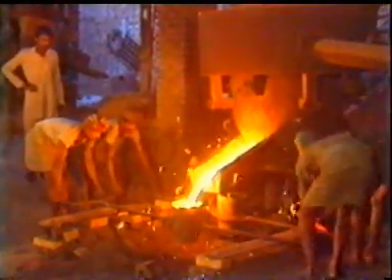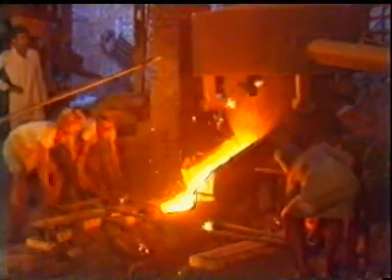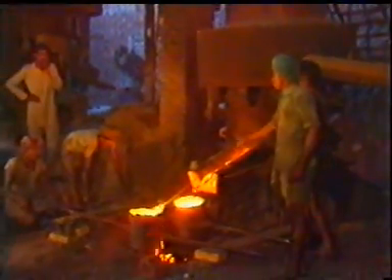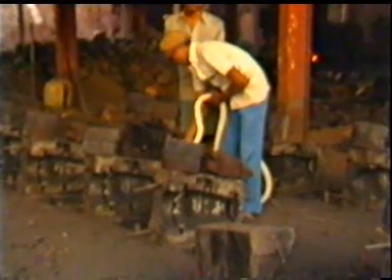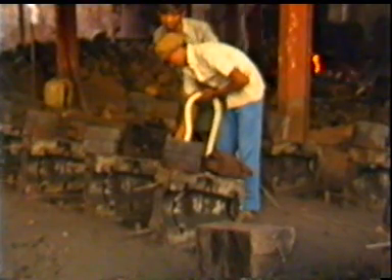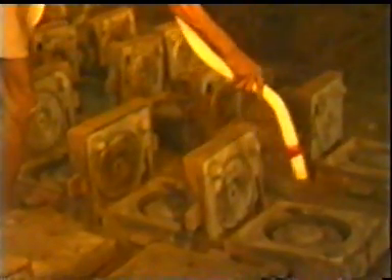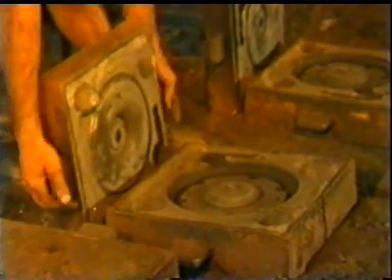The metal from which the component is to be made is melted in a furnace. The furnace may be coal-fired, oil-fired, or electric furnace. Here we have a coal-fired cupola furnace for melting the metal. Before pouring, the prepared molds are cleaned with compressed air. The cope is then placed over the drag and clamped.